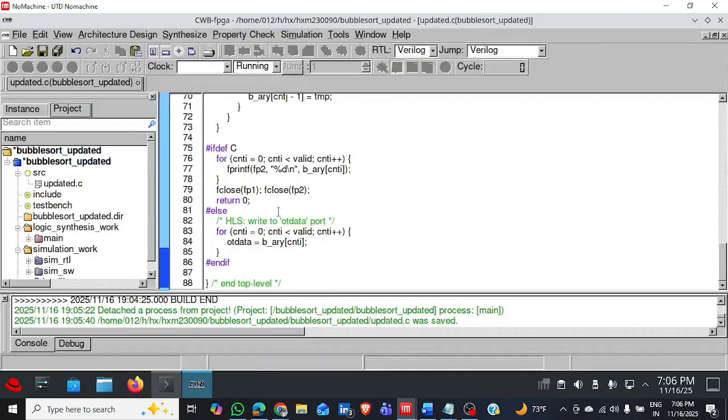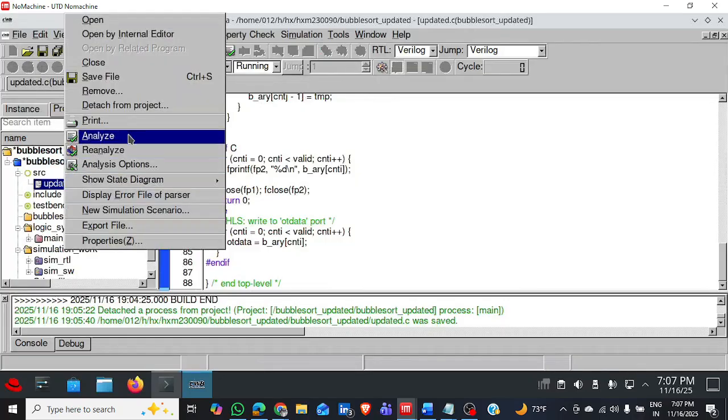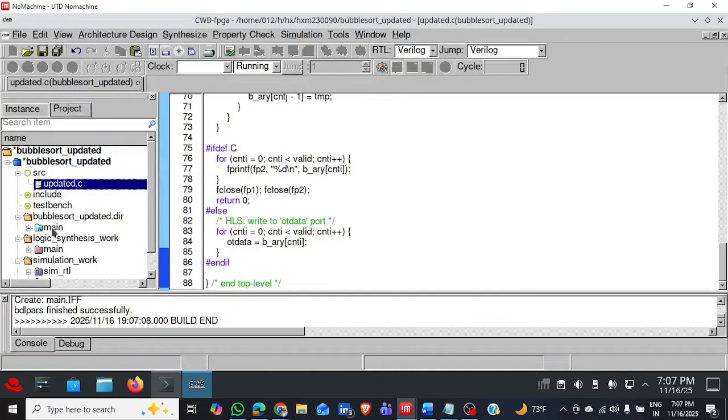So obviously we expect the area to go down. However, BRAMs have a limited number of ports. They can only be read from once or twice per clock cycle. This creates a memory bottleneck. Even though we ask to unroll the loops, the hardware can't run in parallel because every calculation has to wait in line to access the RAM. So obviously we would expect the latency to go up, but not a lot, but yes, it does go up a bit. And then I'll analyze this again for design one.